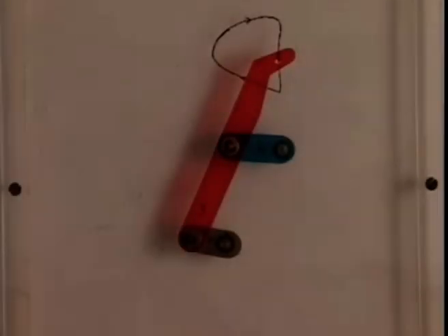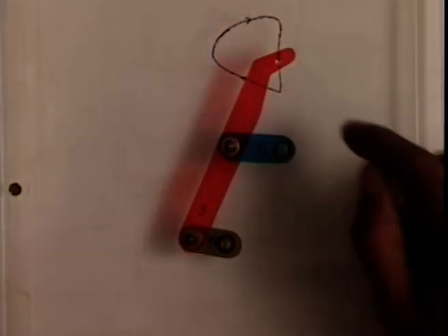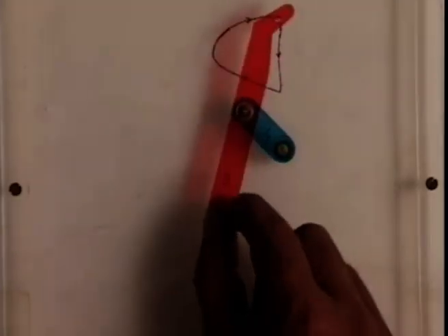As a simpler example of a path generation problem, let us look at the model of this film drive mechanism. As we see, here we have a 4R linkage with this red link as the coupler, and this particular coupler point generates the coupler curve, that is, it is the prescribed path through which this coupler point has to move. So if we now move this 4R linkage, as we see, that particular coupler curve is generated by the coupler point.